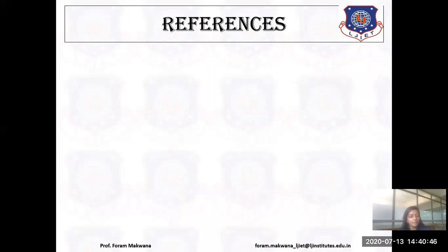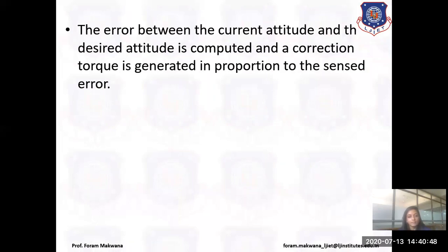As well as the transponder. So first of all, what does transponder mean? As I have told you, it has two types, active and passive. An active satellite has an active transponder, which receives the signal, amplifies it, and retransmits it back to our Earth.